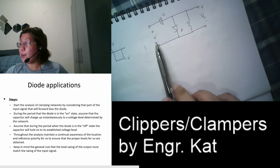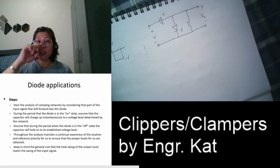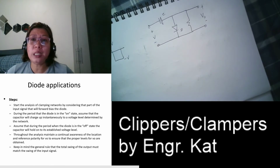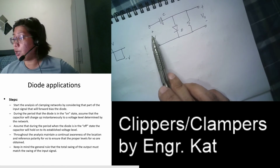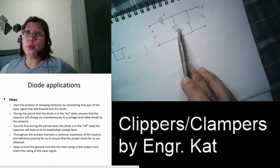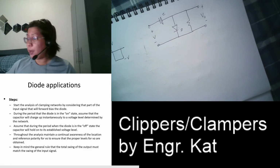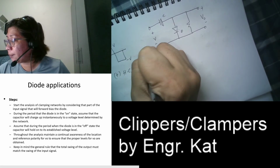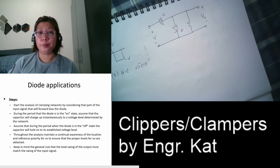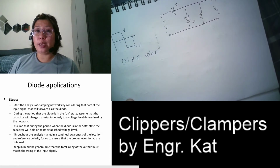But since in this example, during the positive half, your diode is right away forward bias, then we can start. So we have to start the analysis of clamping networks by considering that part of the input signal that will forward bias the diode. During the positive half cycle here, plus, and then this is the anode, so it will be forward bias, then we can start during the positive half. So your diode is on, so we can start.